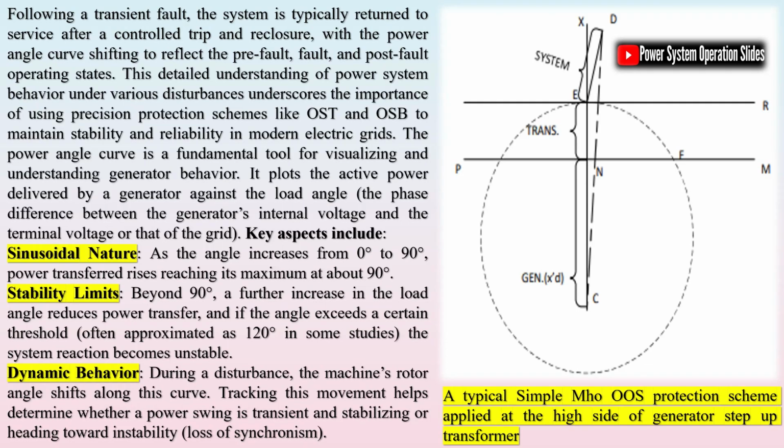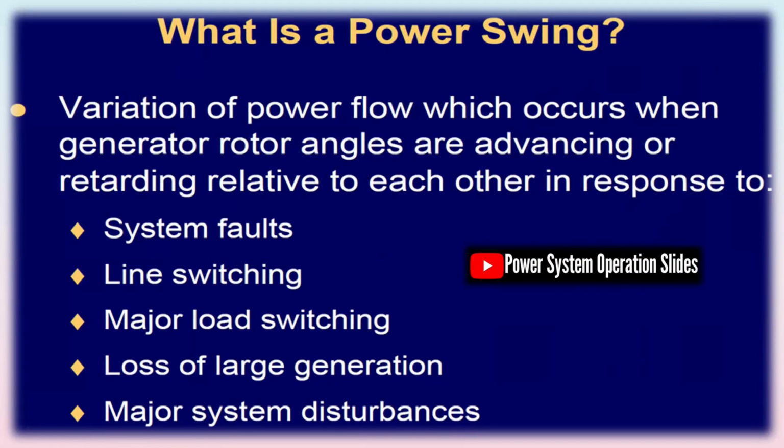Power system stability refers to the ability of a power network to regain equilibrium after experiencing disturbances. Under normal operating conditions, all generators work in synchronism, maintaining a balance between input mechanical power and electrical output. Stability studies are typically classified into small signal or steady state stability, concerned with the recovery from minor load variations and control actions over tens of seconds.